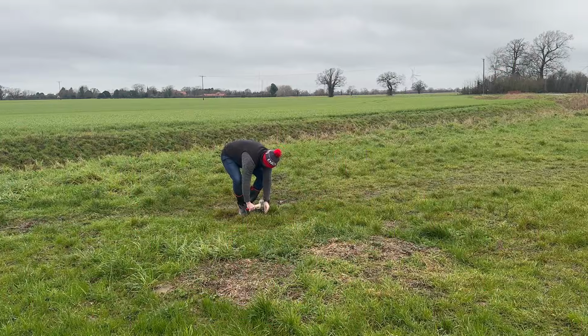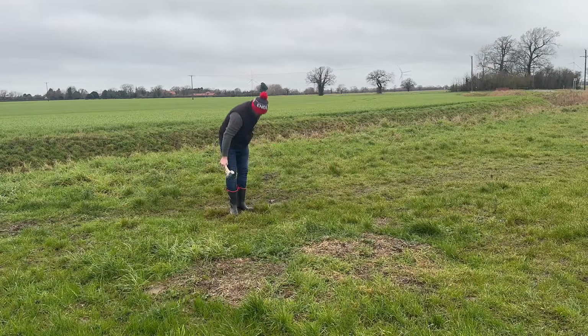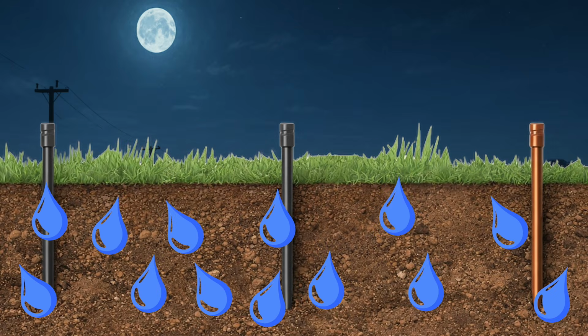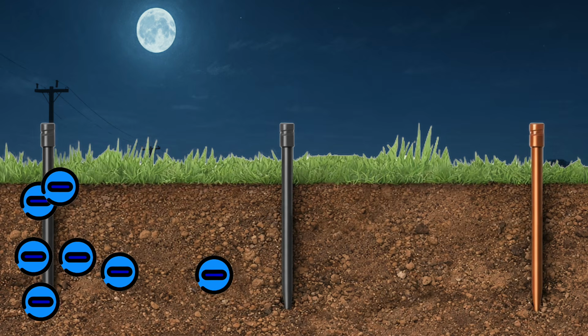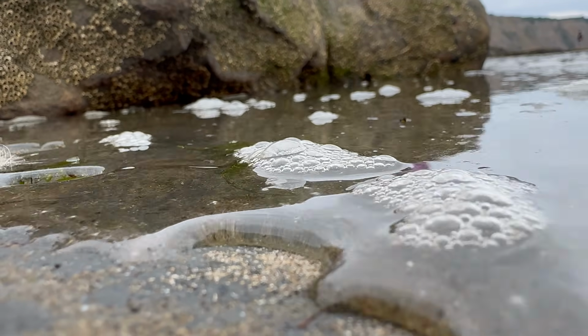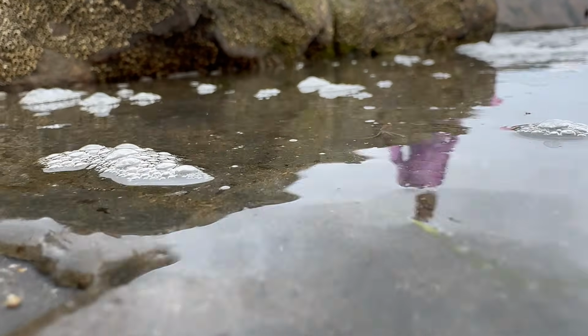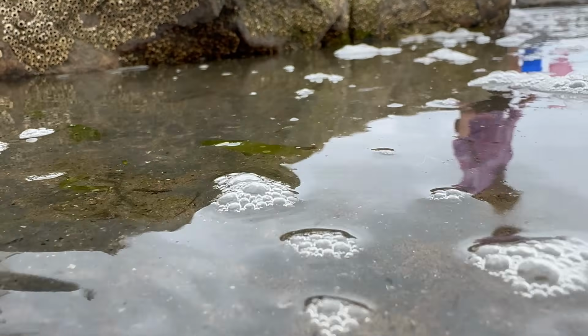Before we talk about earth rods, electrodes and the test results, we need to talk about the ground itself, because resistivity is the property of the soil, not the metal that we drive into it. So what do we actually mean by soil resistivity? Electric current can flow through soil because moisture in the ground contains dissolved salts, and those salts allow ions to move, which is what carries current. That means the ability of the soil to carry current depends on how much moisture it holds and how easily that moisture can move. And this is where resistivity comes in.